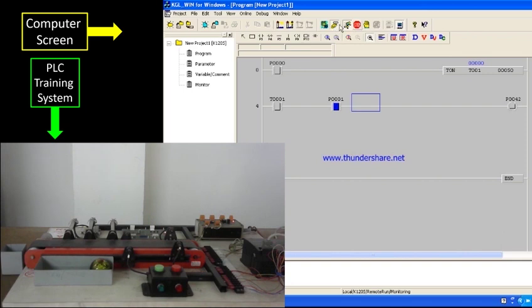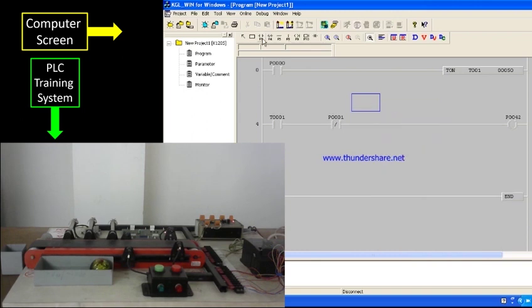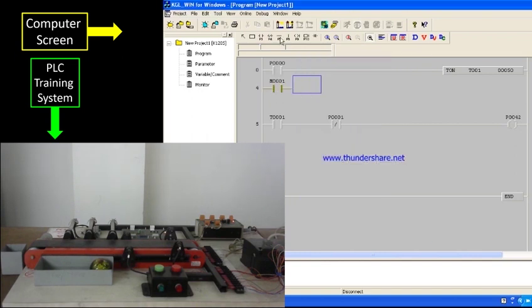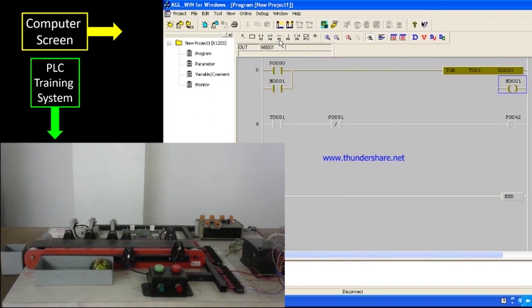So we need to stop it and disconnect it here. Let's insert some lines here, and for latching what we can have is a relay. As we said, we need to use relays for different purposes, and we can have a relay here, and we need to connect it through a number of horizontal lines and then a vertical line. Okay, I think we are good to go.